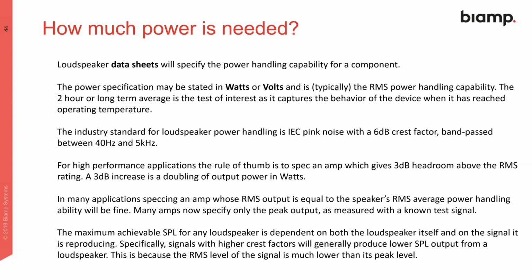Well, your singing is the RMS value. The snare drum hits are the crest factor. So if we've got 15 dB of crest or 22 dB of crest, your RMS value is pulled down. You can artificially boost it by adding limiting on the top end to squash that snare drum hit so it's not as loud relative to the singing and raise your RMS levels.